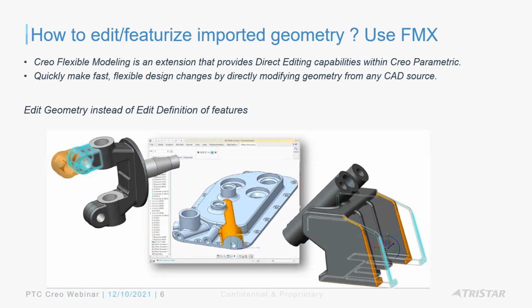Because it doesn't bring in feature history, obviously, it just brings in the geometry and the component or assembly structure. The constraints are all set to fixed, so you can still make changes to it using flexible modeling extension or FMX. Some of you may have heard of it. This also used to be a purchasable module when PTC introduced it initially. Then they started including it in many of their packages.